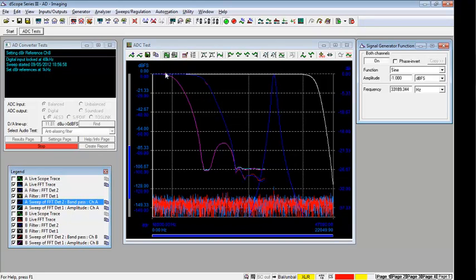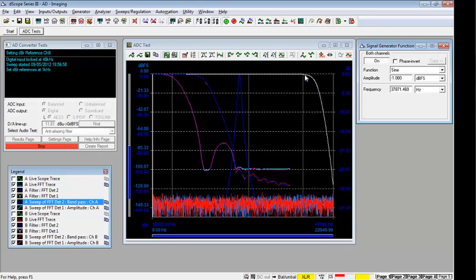But we have another result here in pink, and the pink result is basically produced by the measurement filter here in white. And this is just simply a low-pass filter rolling off at 20 kilohertz, the normally accepted upper limit of human hearing.